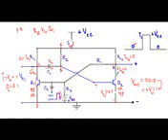When the transistor Q2 is in on state due to the stored charge of the capacitor C1, our collector and emitter terminal will again get shorted. Therefore our output voltage will have a transition from VCC to 0 volt. As the output voltage is reduced from VCC to 0 volt, the voltage difference between this point and this point will be equal to 0 volt, and that 0 volt will be applied between this terminal and this terminal, and this is the emitter terminal of the transistor Q1.